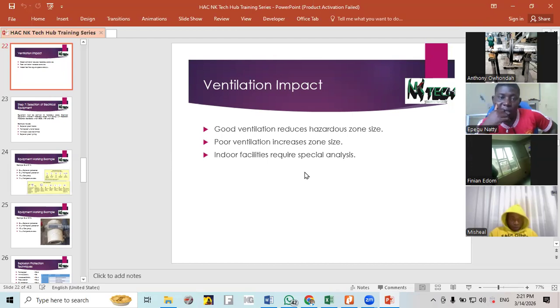Okay, so I would say that your observation is quite correct. But then, you know, your vessels, you can't completely remove oxygen from them. You have breather vents that are open. So there's no way you can tell me that oxygen will not be present, at least a very small amount. If there is anything inside, it can cause an accident. Let's say a lightning strike can cause accidents inside the tank.